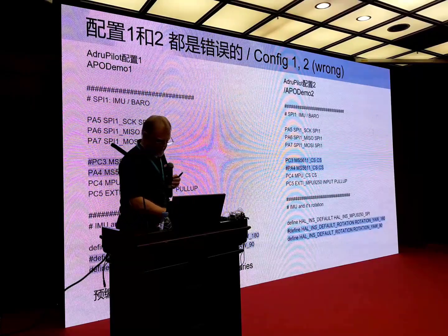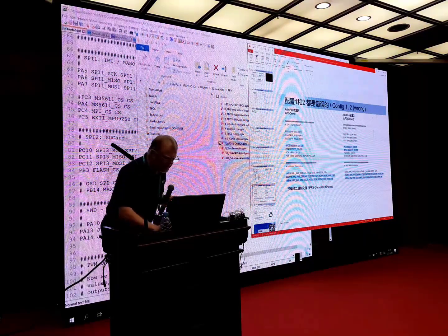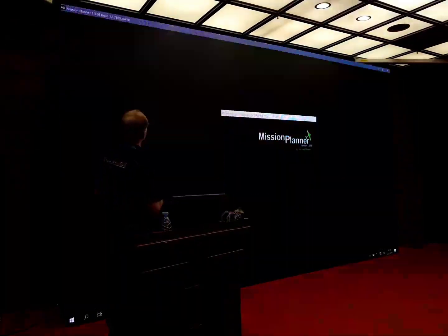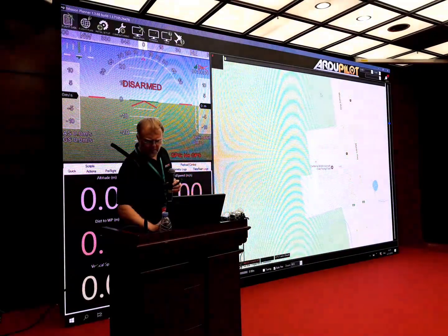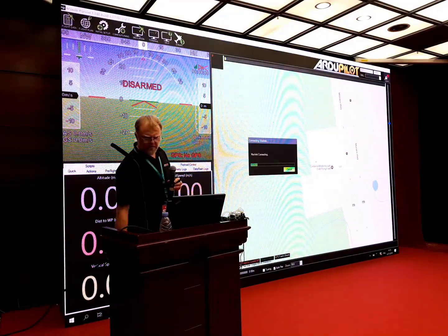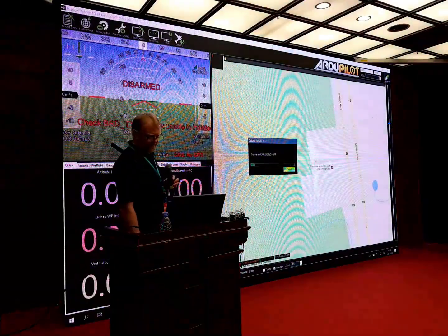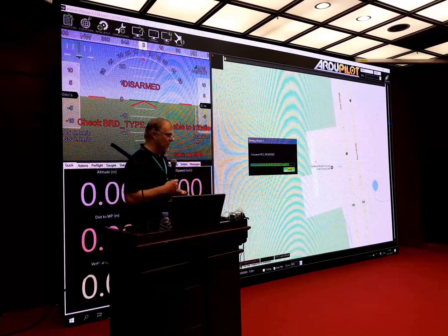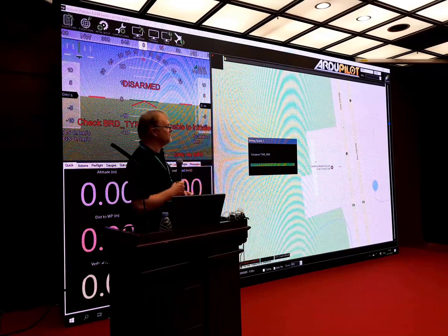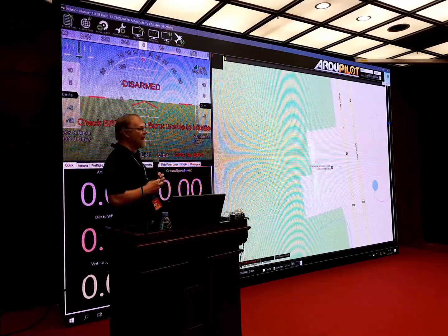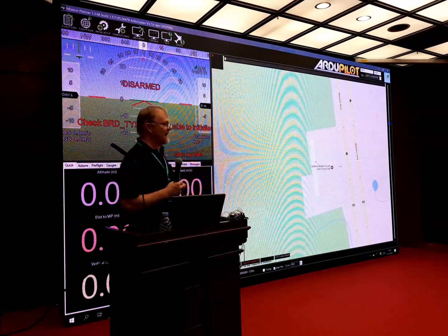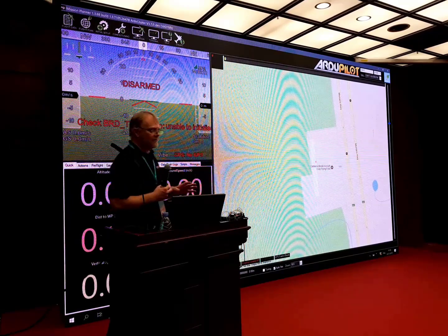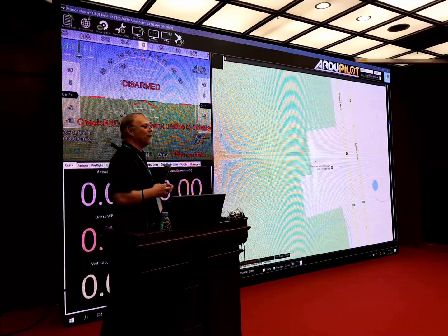So let's just go. Now where's my Mission Planner? There. Right. We have it on COM17. All right. So immediately we can see that something is wrong. We messed up something because we cannot initialize the barometer or anything like that, because the chip selects are incorrect. If I would now start moving the cables, it would actually start working, but I don't want to touch the cables. So I'm going the other way.